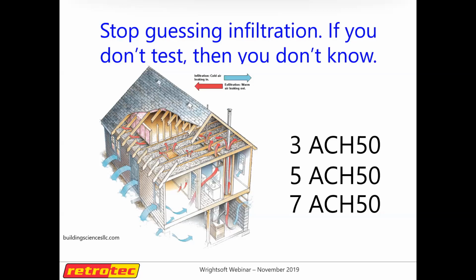Mm-hmm. Yeah, or we even support test C, test N values for multi-point testing. If you want to, I know all the code books. So like if you're doing new construction, it's going to be all ACH 50, CFM 50 kind of stuff, because that's the standard to do a single point test. But I'm sure you have tutorials that get into this elsewhere, but multi-point testing can definitely be more accurate than a single point test, and we support entering both types of field measurements.